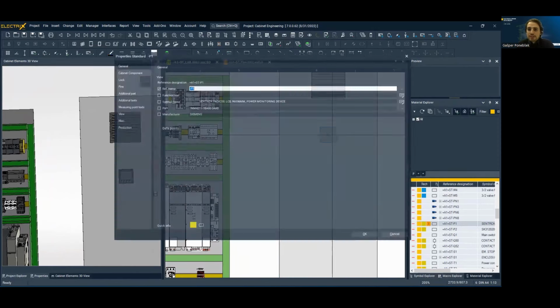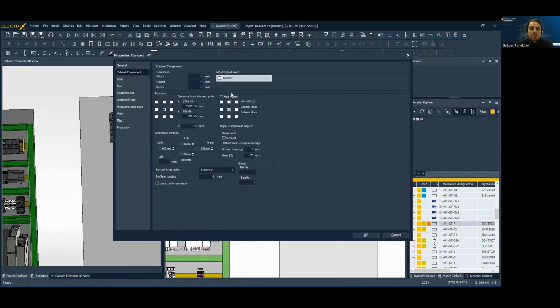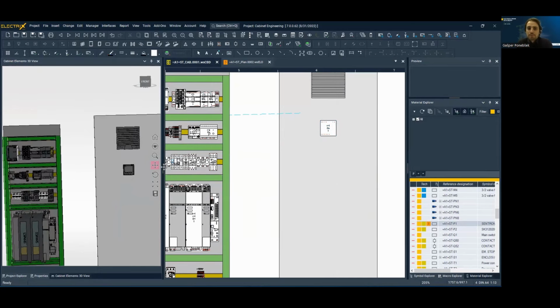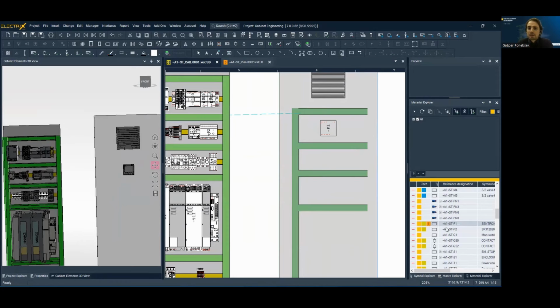If we check these cable ducts, and we can place it on the right position to write the proper dimensions. So Y coordinate is -490, and that's it. Now this HMI is on the right position on the door. So before, you saw some cable ducts here. These are virtual cable ducts. Actually, they are placed on the opposite side of the door, and we can place these virtual cable ducts.